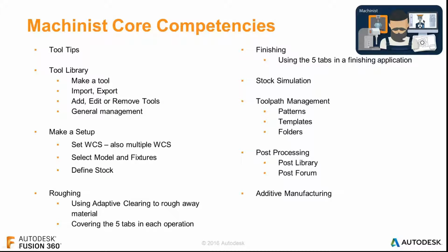Adaptive clearing, the way it works is really great. It makes it very easy to optimize the tool loading. We'll have a look at a few options in the programming process to ensure the tool wear is even, that things are maintained very cleanly. The interface itself is also really consistent when it comes to generating toolpaths. We're always going to have the same set of tabs to work through, either roughing or finishing. You just put in the information and go from there.